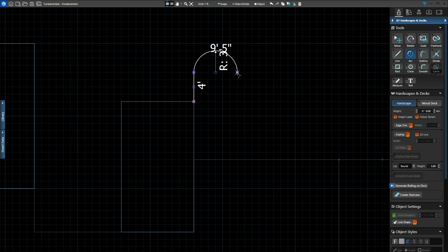So we can use the outline tool to create the other side of the shape, similar to what we did with the kitchen island. Let's activate our outline tool. Take your cursor over to your toolbar, and on the second row of tools, click on the outline tool. We'll have our question mark on our cursor. What shape do you want to mirror or outline? We'll left click on either one of the yellow squares on the ends of our partial shape. Then we'll come in with the offset function. Left click when you get 1 foot inset. So we're going to stretch that offset in 1 foot and left click to complete our shape.